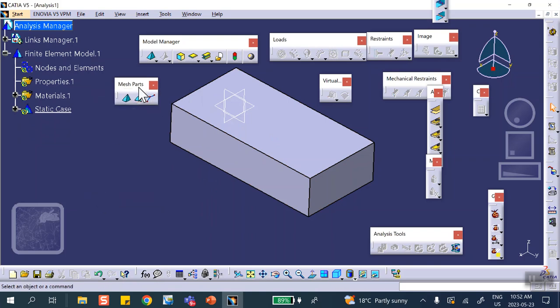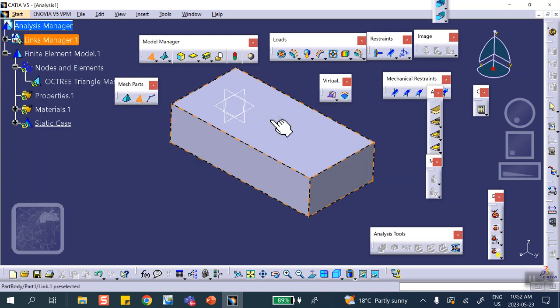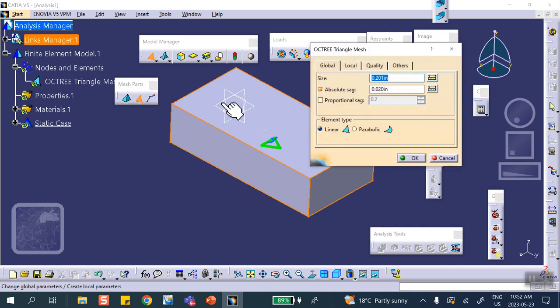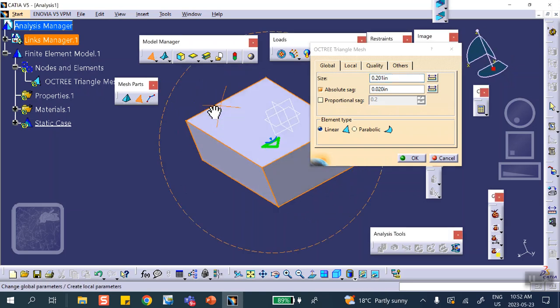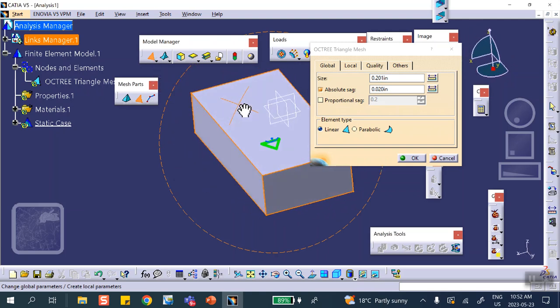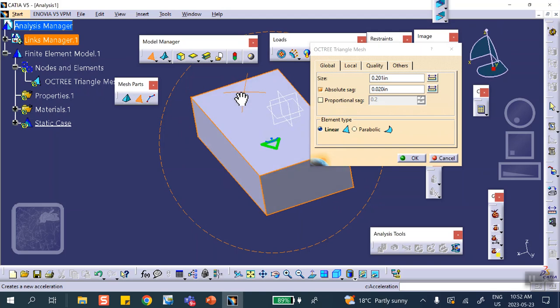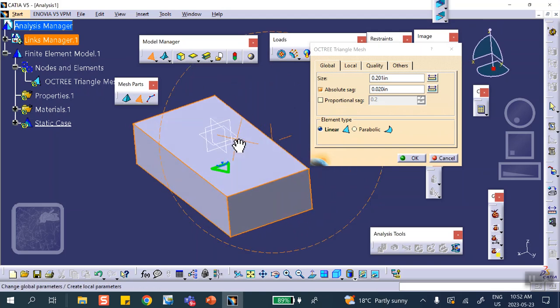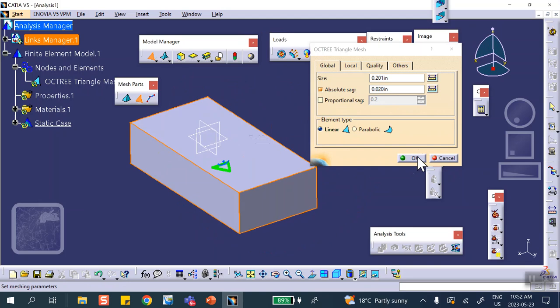I have to, first of all, get a surface here, but I don't have a surface here. Because, look, if you clicked on this and you tried to take the box, it'll do it for you. Let me show you. It'll do it for you. But it does the entire box. In order to mesh that surface, it creates the surface automatically for you, but it does the whole thing. And I don't want that. So essentially, this becomes like a shoebox, a hollow box. That's not what I have. I have full sheet metal.